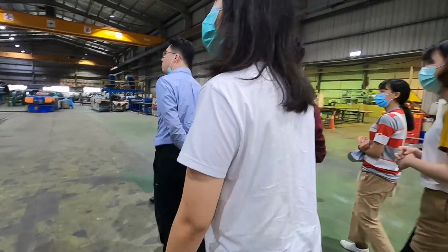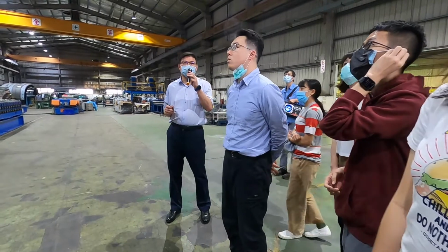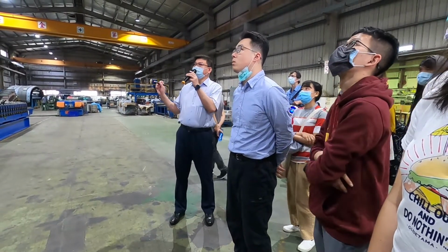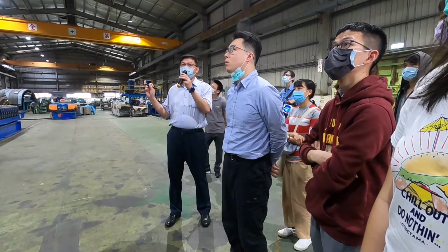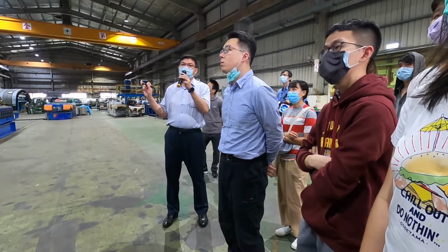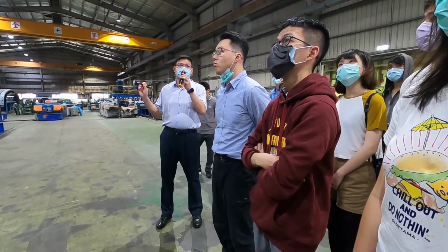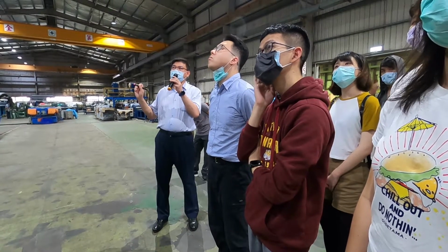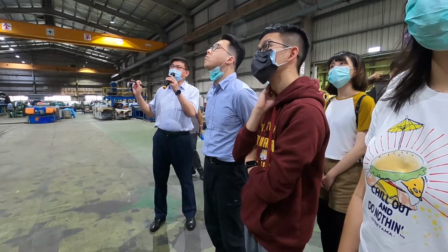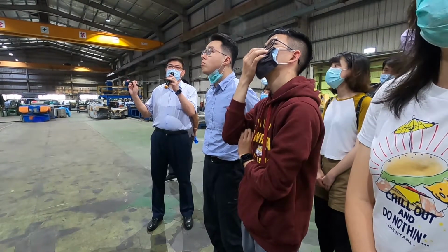During the design, there were some physical criteria requested by the architect. The ceiling is required to achieve an acoustic value of 0.9 alpha, meaning 90% of the noise will be absorbed by this corrugated panel. And on top of this corrugated panel, there is rock wool for insulation.